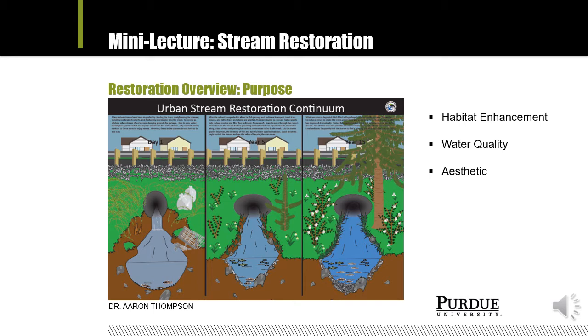It can be a multi-goal project, but depending on which goals are being prioritized, it's going to change how you approach the specifics of laying out future revisions to that stream, to the channel, and what species you're managing for. So if you're managing brook trout, there are specific requirements related to how much gravel needs to be on the bottom and not be exposed to heavy sedimentation. Lots and lots of details go into this.